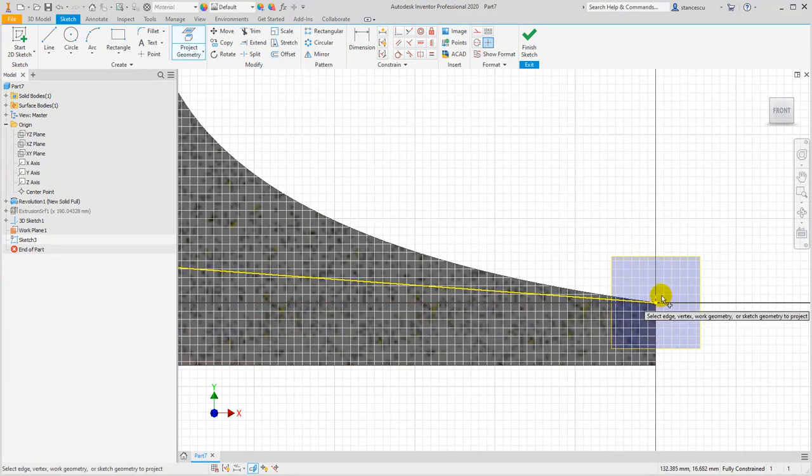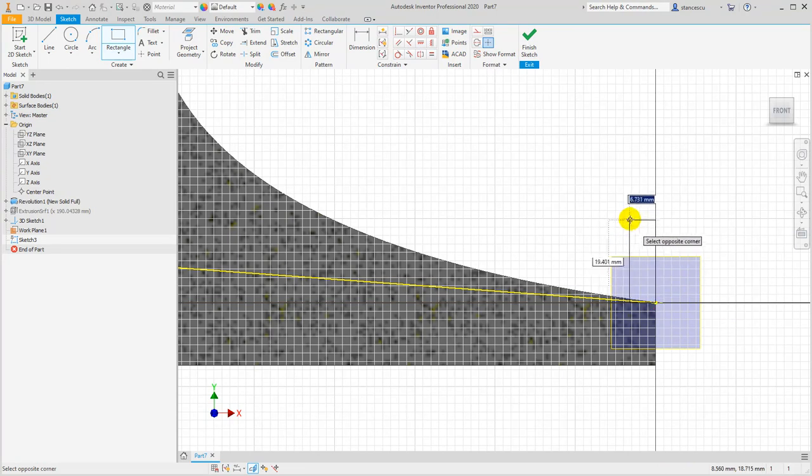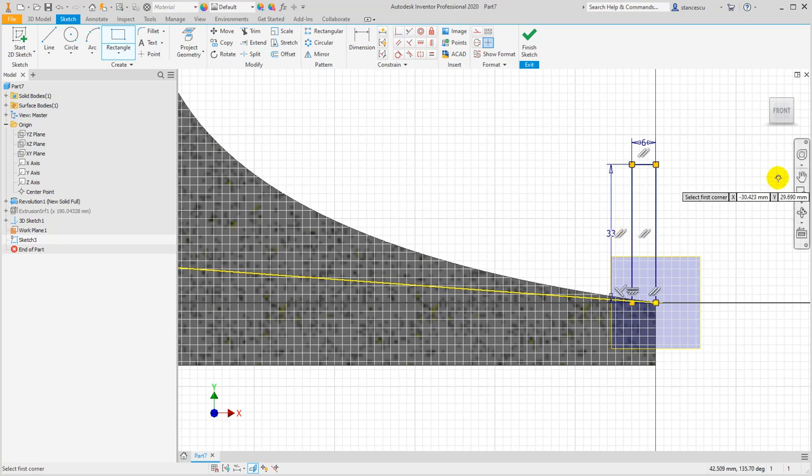You see here the point drawn, and now we choose rectangle starting from this very point, 6 horizontal, the key tab. This is learned today, yes, tab, to introduce 33 for the vertical side, 33 to 6.